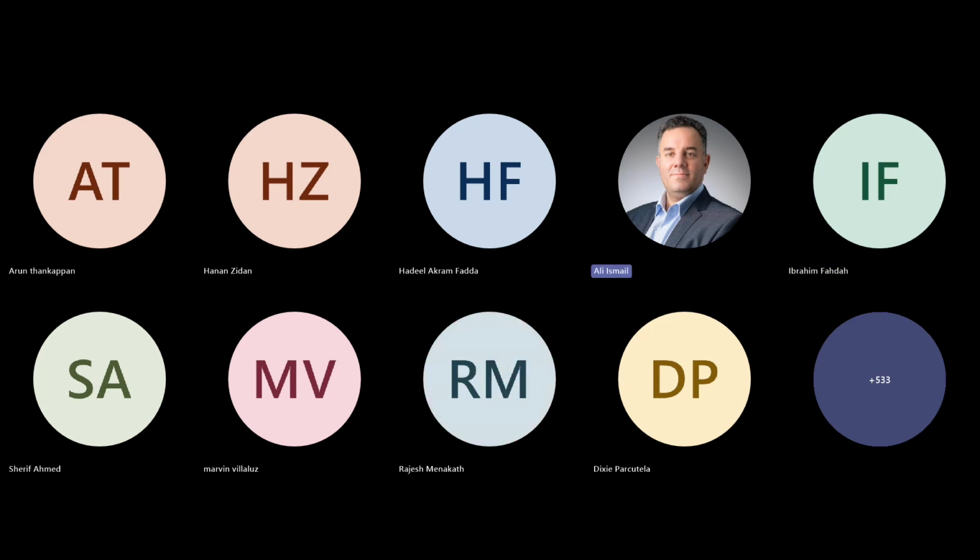Okay. Relating to the question of how to check the fire rating if the finished materials are not considered, it is the same case as what you are doing now when you submit to civil defense, where you indicate the fire resistance of internal walls, external walls, stair walls, emergency doors, etc. So it is just a parameter where you indicate if the fire rating for this wall is 1 hour or 1.5 hours, etc.